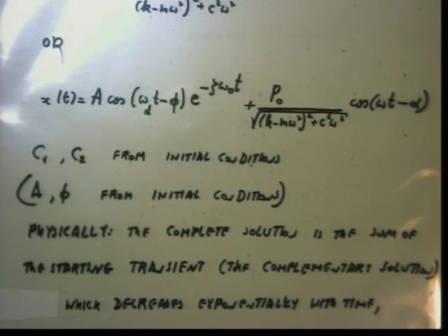We call it transient because there is e to the power minus something times t. Because it disappears when t is big. It's gone. Very often, if zeta is a bit sizable, then it goes very, very fast. So there is some initial effect, and then there is something that stays forever.